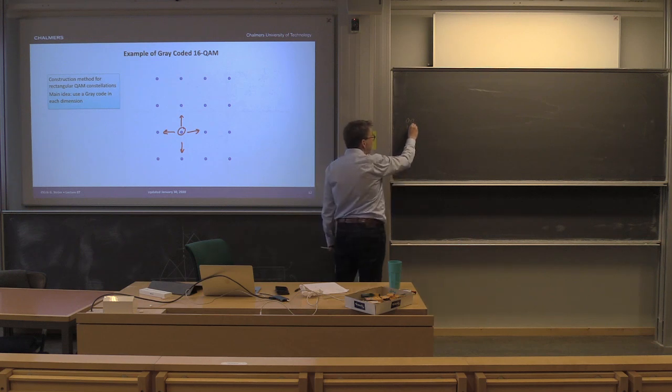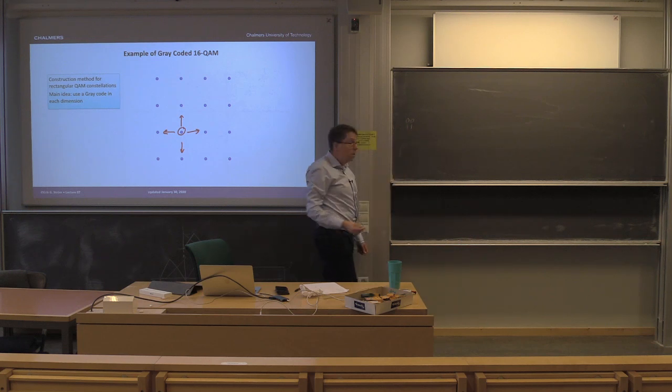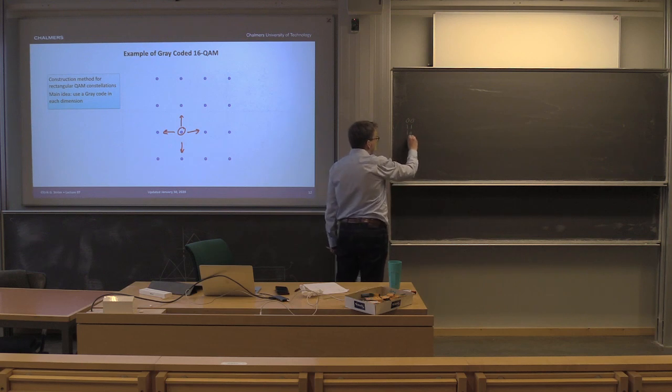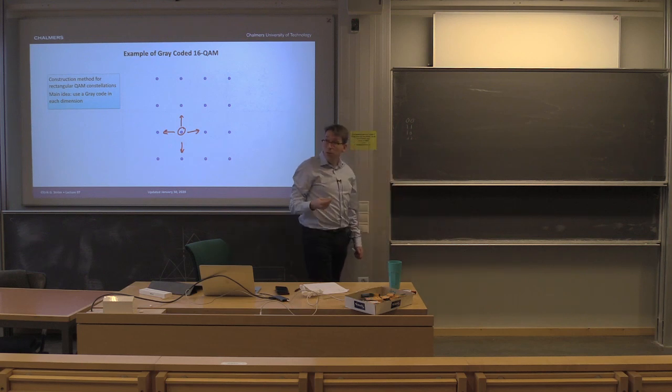You can use a really bad constellation, but you use a gray code for that also, for 4-PAM. For two binary symbols, it doesn't matter, of course. But for all others, you can use a gray code. And there are gray codes for any constellation with a fixed number of bits, from one bit, two bits, three bits, and so forth, up to infinity. So it's easily constructed, and it works in two dimensions also.